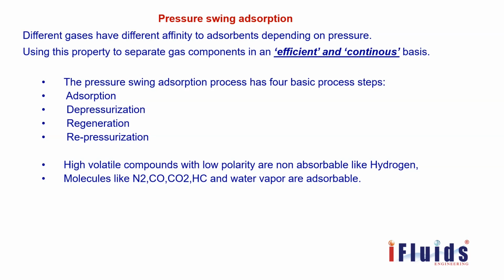Desulfurization of kerosene, desulfurization of diesel, naphtha, isomerization units, hydrocracker units, all these units consume a lot of hydrogen. So a dedicated hydrogen production unit is required for every petroleum refinery. That's why hydrogen production is being discussed in the journey of petroleum.